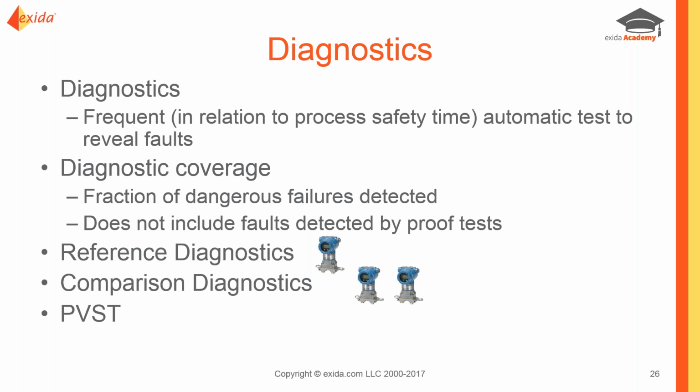It uses slightly different techniques, but depending on how it's set up, the diagnostic coverage you're going to get is continuous monitoring. Now, this is not the same as the faults detected by our proof test coverage. These are dangerous failures that can be detected while we're on stream, and the real advantage is you can identify those failures and get them corrected immediately instead of running in a failed state for the period of time between proof tests.